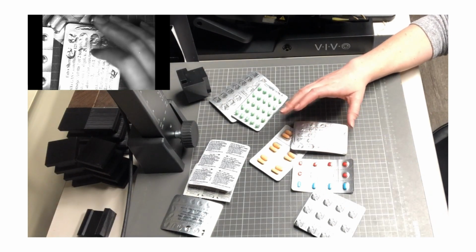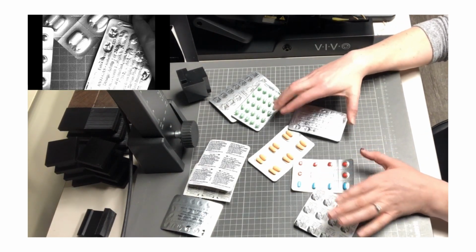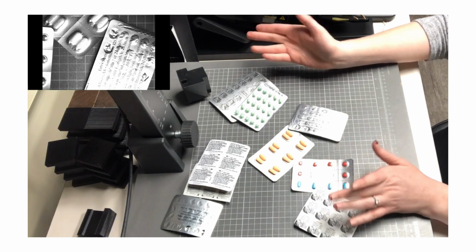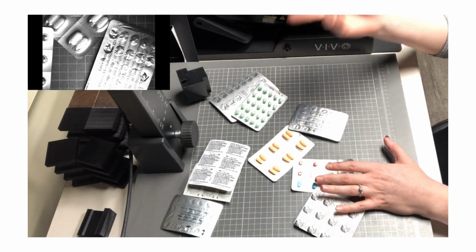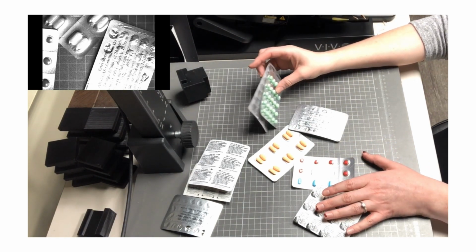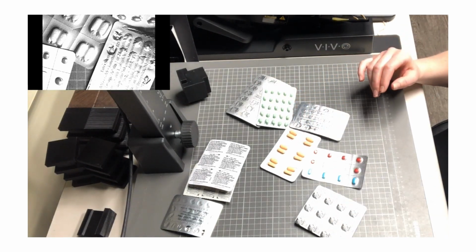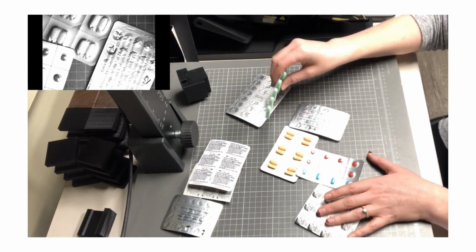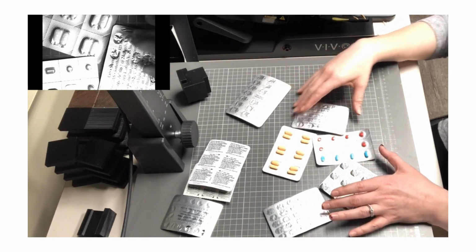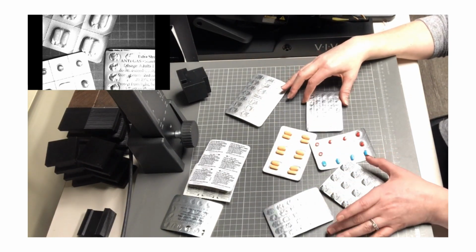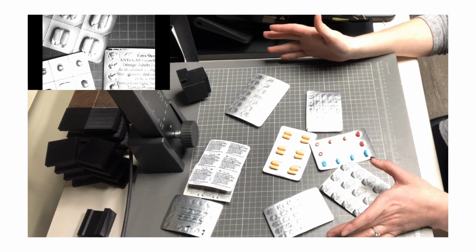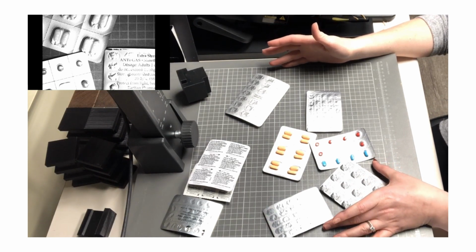So it looks like we're inspecting both sides, and in the inspection report it did say that both sides will be presented facing up, so we can put a camera there. So we already know we're at 2 inspections from the get-go. Starting with the top inspection, because we're reading text, I can remove the idea that we need a dark field inspection.